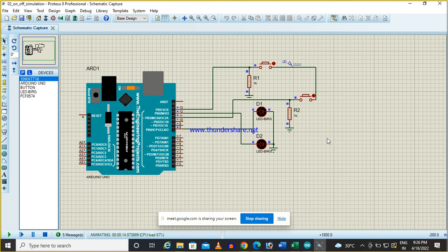There will be interlocks. When we are going to turn on some system, it will check a lot of interlocks, and only after checking this will your output be enabled. Simply, in an aircraft or a nuclear reactor, where a lot of safety aspects are involved, a lot of inputs will check the status of the system, and based on that only it will allow the operator. Even though he is pressing, only then will the output be energized. So at that time you have to collect all the inputs and outputs.